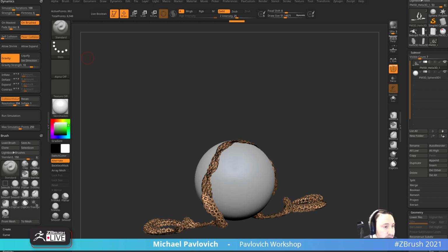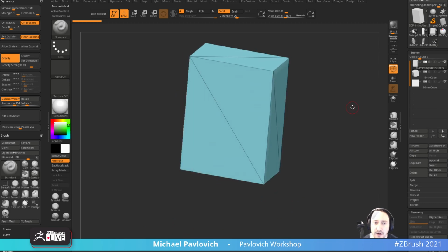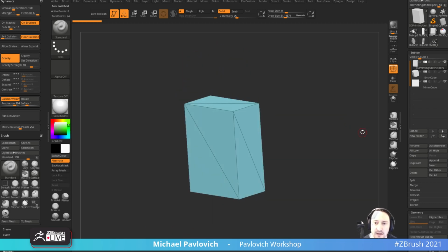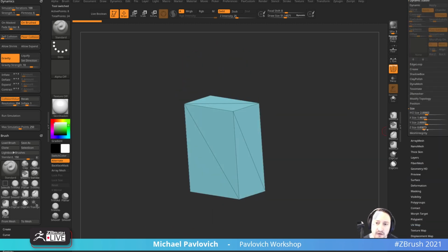And make sure when you export your model from ZBrush, Maya, Blender, or 3ds Max, it's the exact same size. Oftentimes the model is super small. The easiest way, if you're working at a certain scale in another program, is to bring a 1 unit object exported from that program into ZBrush, and it'll do that automatically. It's exactly what I was talking about when I brought these in. I made these in Fusion 360, imported them, and it did those conversions for me. It keeps it at ZBrush scale here at 2, so it works nicely.